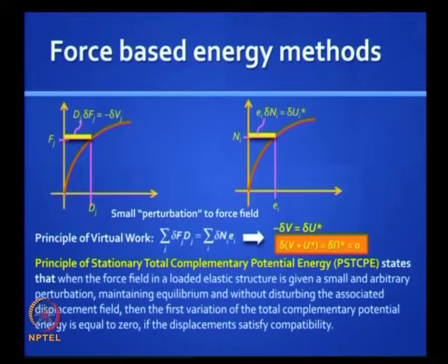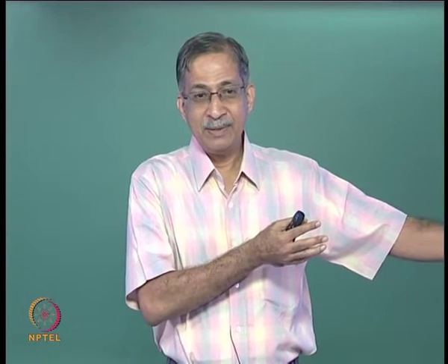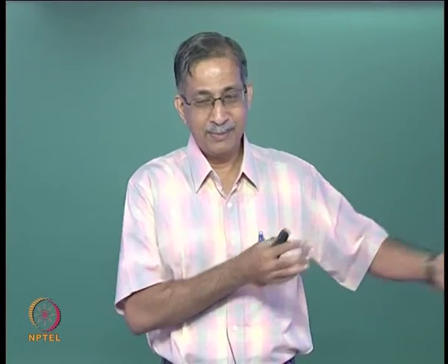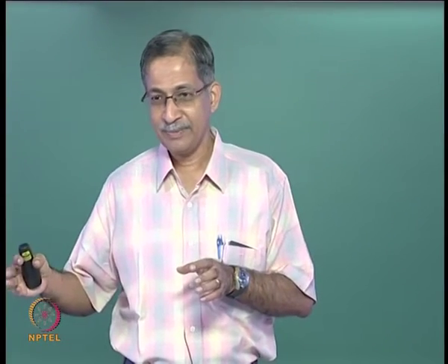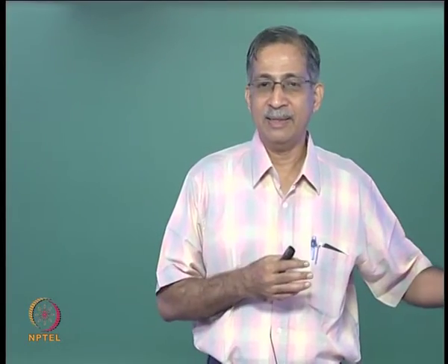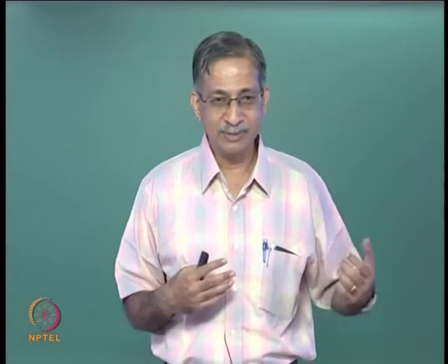The format is the same, but there you are disturbing the displacement field. Here you are disturbing the force field. When you are disturbing the displacement field there, you are not changing the forces. When you are disturbing the force field here, you are not changing the displacement. So that is important to note. It is something you do in your mind. It is arbitrary and it is of very small value, and the cause that you refer to here is perturbation and the effect is variation. Those are the terms used.